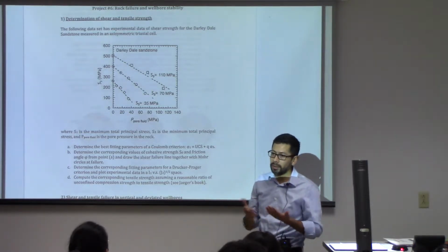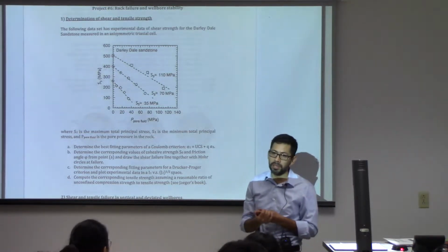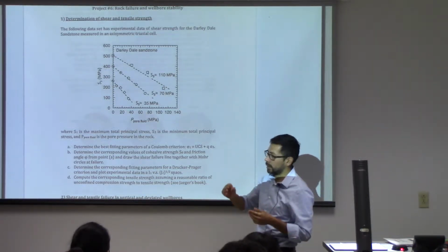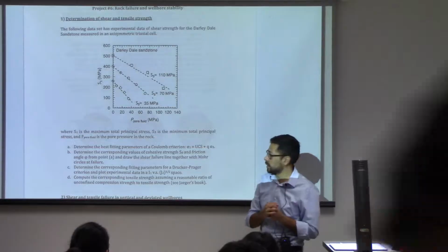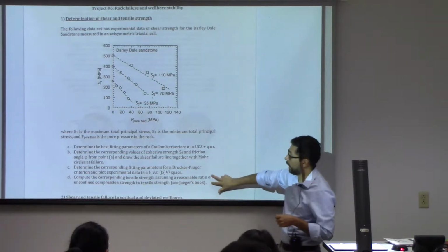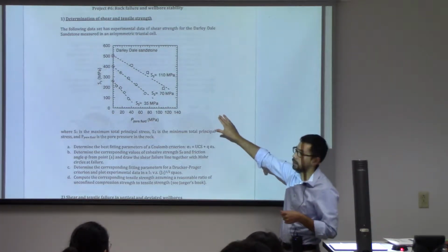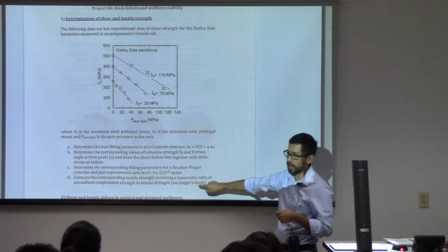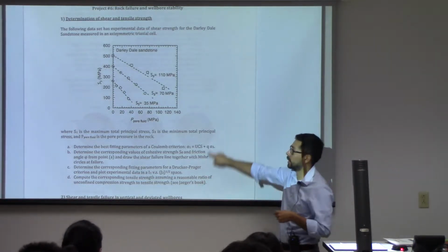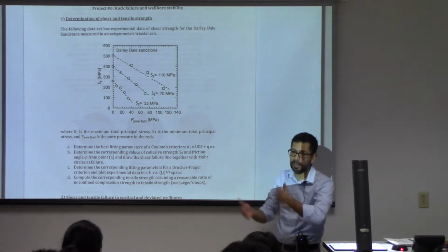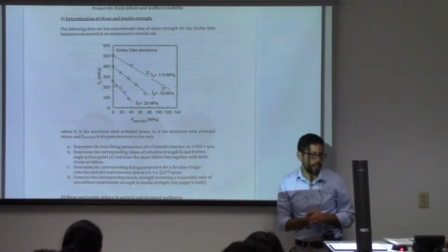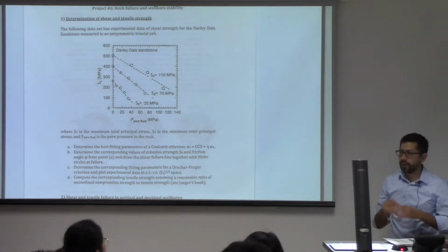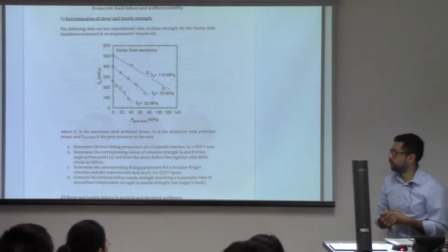So with that, you will be able to say when there is shear failure around the wellbore, and also you need to know what is the tensile strength. For that, we don't have measurements for this particular rock, but if you read the part on tensile strength in Jaeger's book, you will see that based on shear strength, you can get an estimate of a reasonable tensile strength. And all of that, we're going to put into wellbore stability.